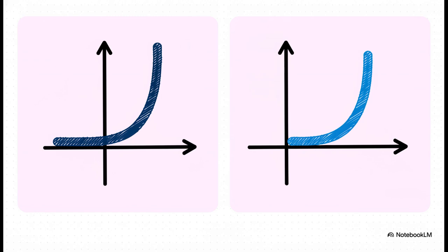Both types of MOSFETs are what we call square law devices, meaning their transfer curves are parabolic. But their equations tell 2 very different stories. The D-MOSFET, because it has that physical channel, acts a lot like a JFET. It conducts fully at 0 volts and requires a negative cutoff voltage to shut down.